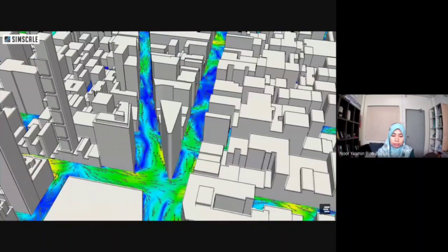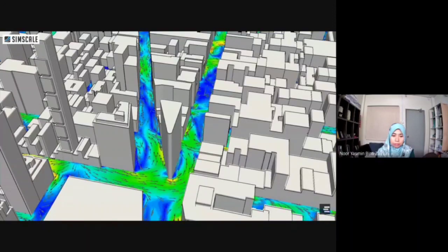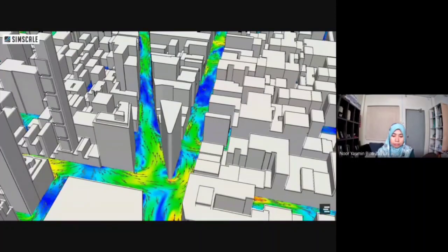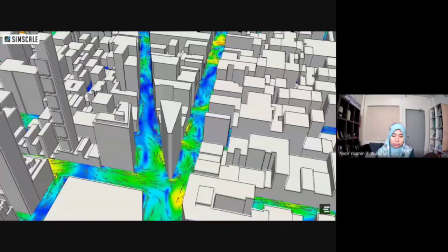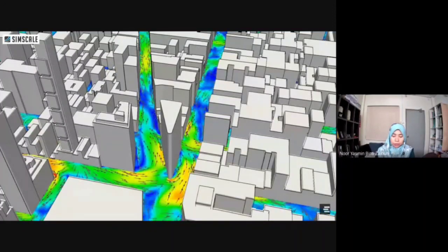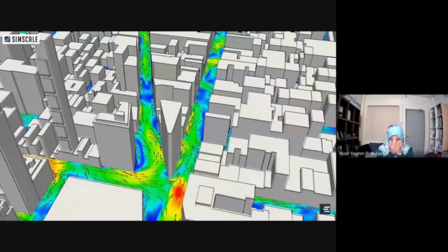The animation, kindly provided by SimScale, shows the flow speed, where the red color shows the higher flow speeds. In these conditions, the wind gusts reach the front leading edge, the cone shape of the building, which creates accelerated flow and vortices on the Broadway and especially the Fifth Avenue side.